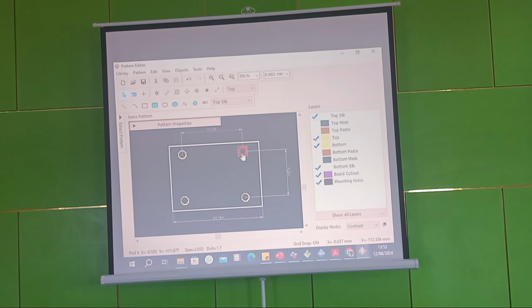Because if you have too much wire crossing, it will look rough. But if you rearrange it on the graphical symbol, make sure you have the right pattern. So by the time you want to do your PCB, it will automatically assign it to the right pin. So that's it.